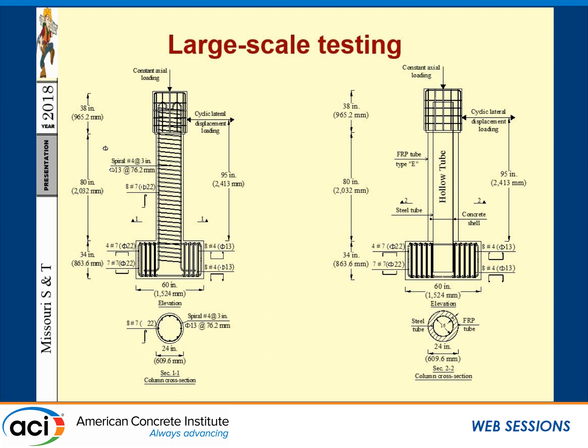So for the hollow core columns, we have the steel pipe that's embedded into the footing. The steel pipe goes into your footing. However, the FRP stays at the surface over here. So the reality is you don't transfer moment on the FRP. Your moment is transferred through the tensile stresses in the steel, which is embedded into the footing. The FRP does not transfer the load to the footing. And then the concrete in between over here. There is no other reinforcement except the two pipes, so we did not use any internal reinforcement in the concrete itself.